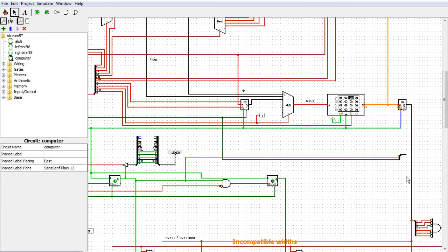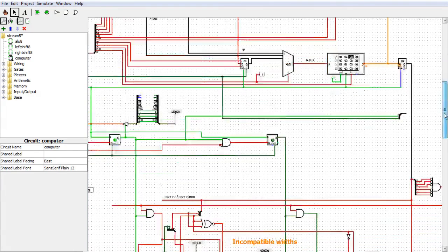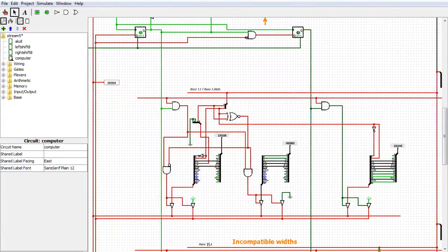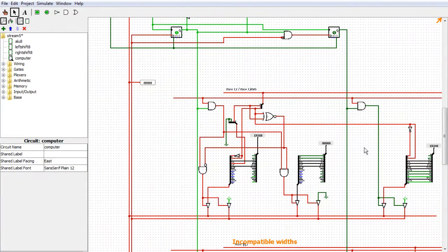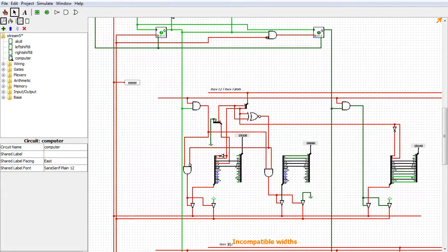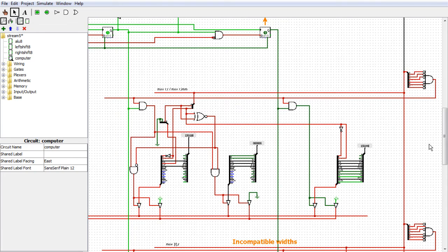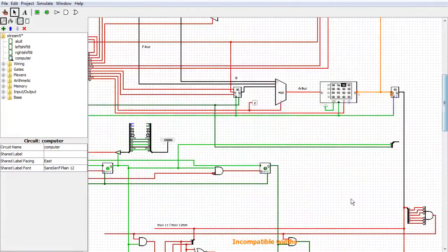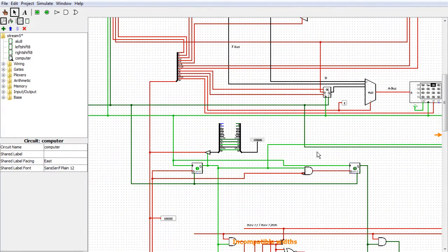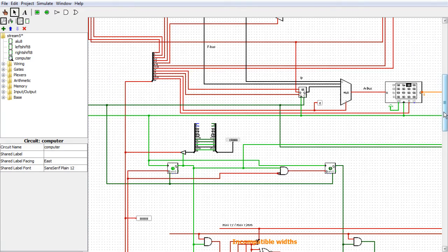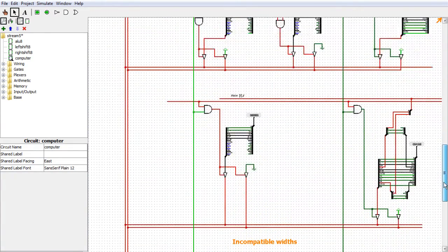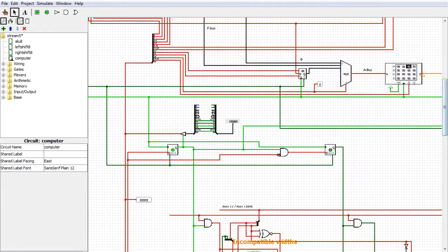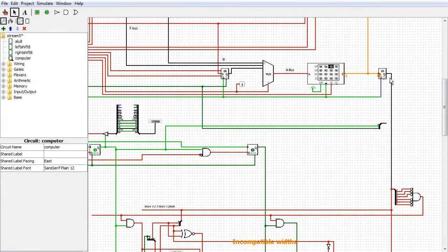So you do it like this, and doing it like this means that you would have to move this instruction over here, right? You'd have to have a wait state for this one as well. And it would have to be executed in phase 2. In fact, you could just get rid of all of these phase 1s here and replace it with just a blanket state up here that does one thing, because every phase 0 now is going to be exactly the same. It's just going to be load the opcode into the instruction latch, or whatever you want to call it here.